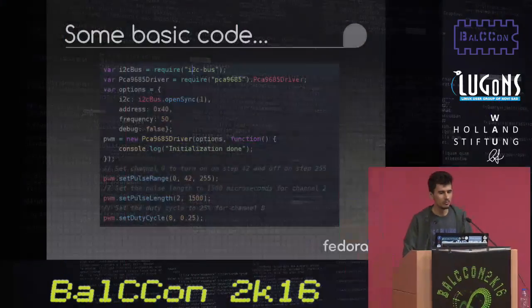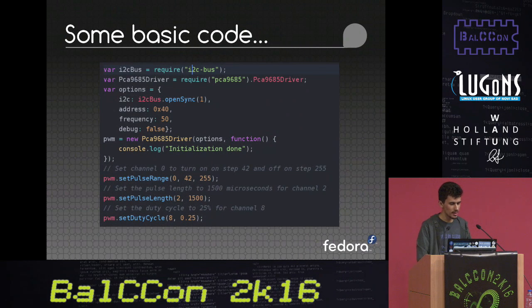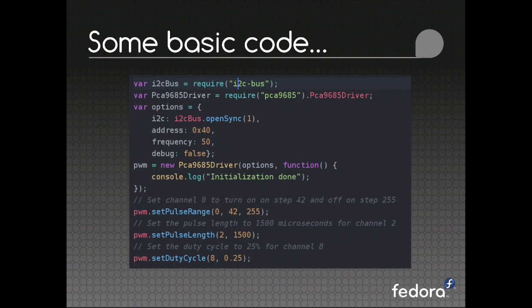And if you want to see an example, it's kind of like this. As you can see, we have to get this line of code before we try to use it. So let's say I install it, and I have to require the first two lines. Okay, so these two lines allow me to control I2C protocols, and this is my chip. And then I just open my address, my frequency. I have to know it from my datasheet. It is kind of technical, but it's the hardware way.